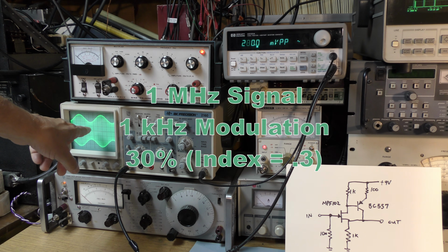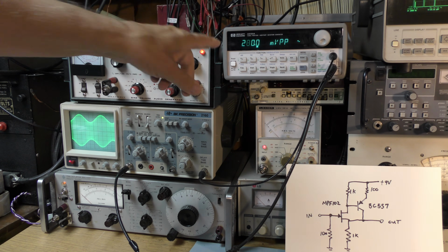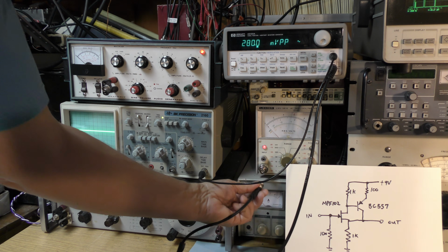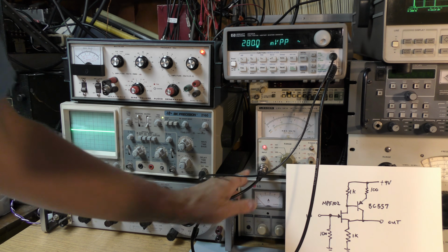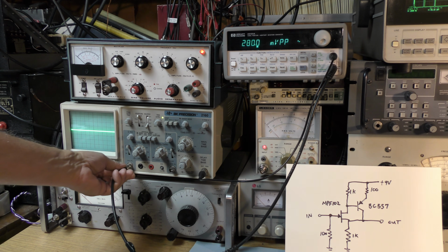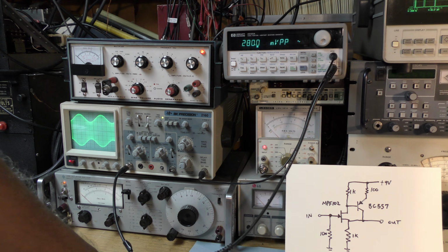Okay, I have an AM signal I've developed over here, and it's supposed to be 280 millivolts peak to peak. 280 millivolts peak to peak. Let's bring that over to our RMS voltmeter. Yeah, 100 millivolts RMS. Okay, that makes sense. So that's a believable number. This is the input signal we're going to be bringing into the crystal radio.